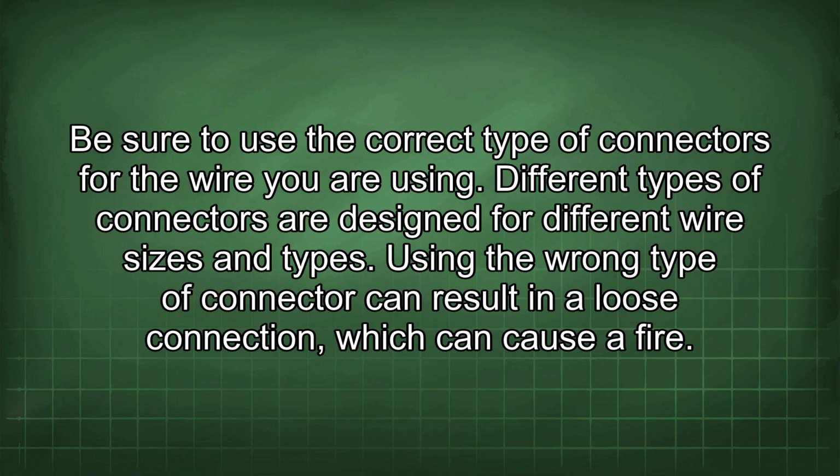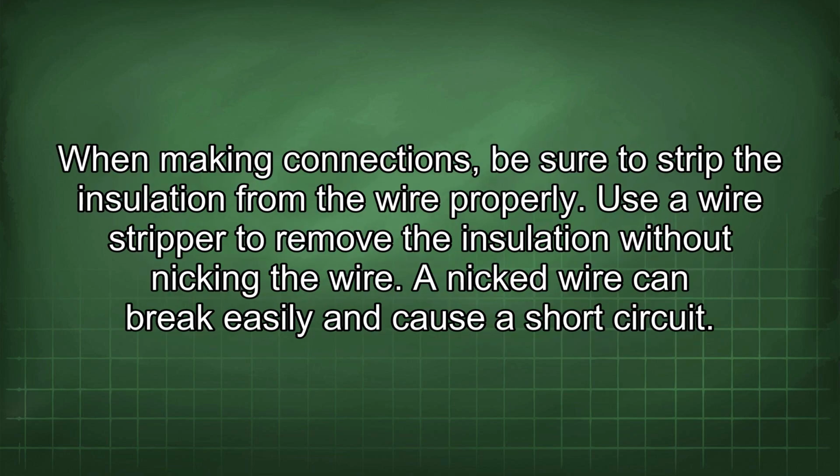Different types of connectors are designed for different wire sizes and types. Using the wrong type of connector can result in a loose connection, which can cause a fire. When making connections, be sure to strip the insulation from the wire properly. Use a wire stripper to remove the insulation without nicking the wire. A nicked wire can break easily and cause a short circuit.